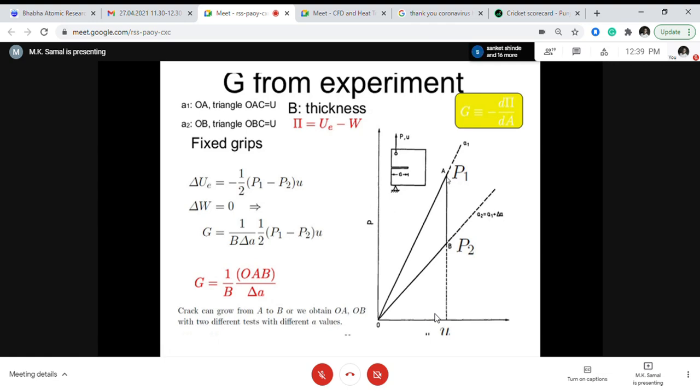So this is the displacement of the body, not of the crack. You see this geometry. This is called the CT, compact tension specimen geometry. You take a rectangular geometry, make a crack, and it has some thickness. In the pin you pull to some displacement. Let us say you pull it to 2 mm, and leave it. You fix it.